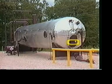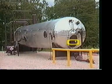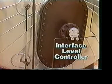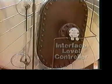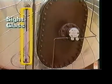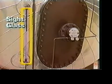In the settling section, the surface where water and oil come together is called the water-oil interface. The interface level controller maintains the water-oil interface level. A sight glass enables a pumper to see the clean oil level and water-oil interface in the treater and helps him determine if abnormal fluid levels exist.